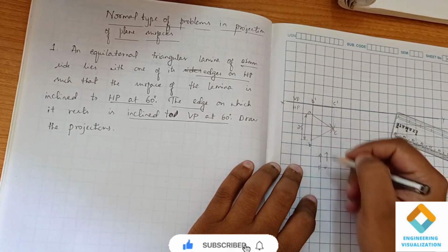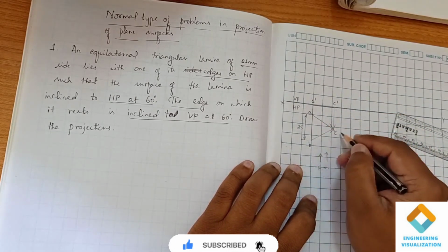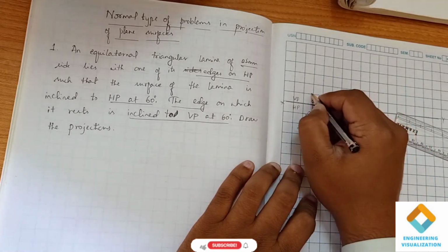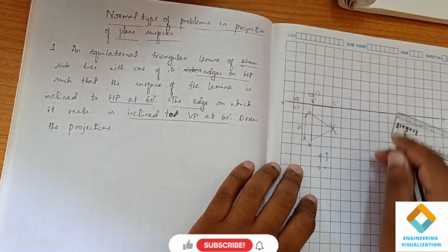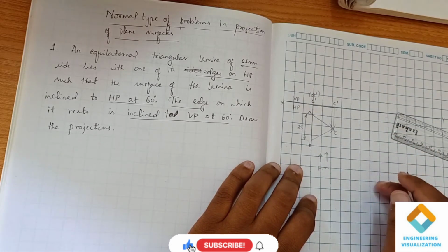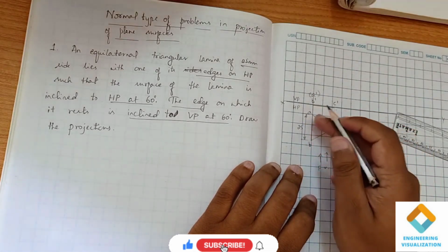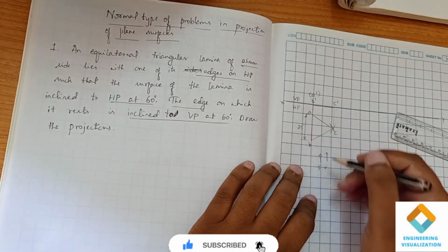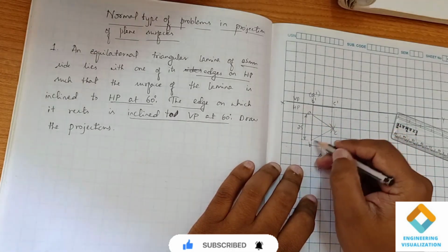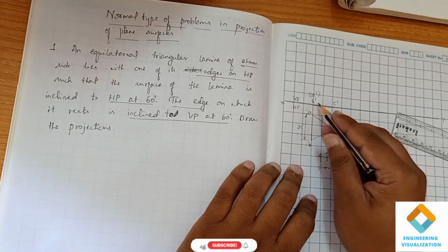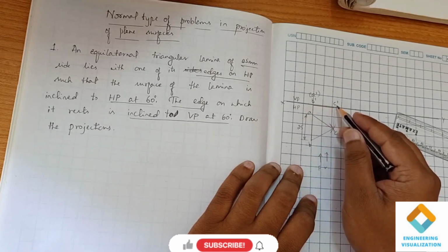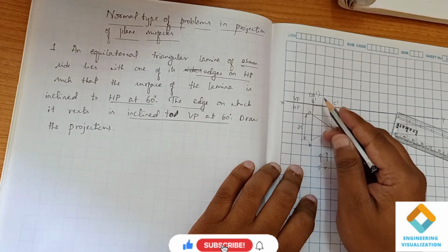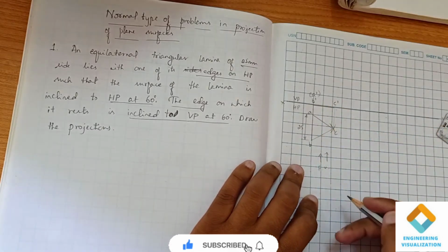But you see, when you are looking from this front view, we are able to see this edge, but we are not able to see this corner point. So this A dash will be in brackets. This is the first position. When we construct the triangle, we get the same dimension of 25. When we project the front view, we are able to see only this edge BC. That's why B dash C dash is written without brackets, and A dash, which is not visible, is written within brackets. So this is the first position.